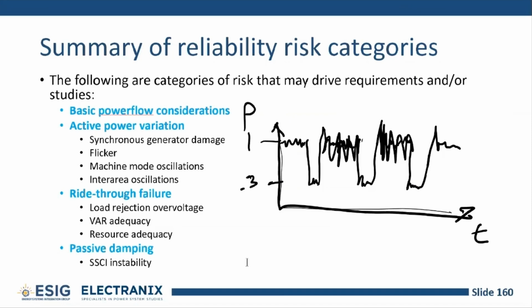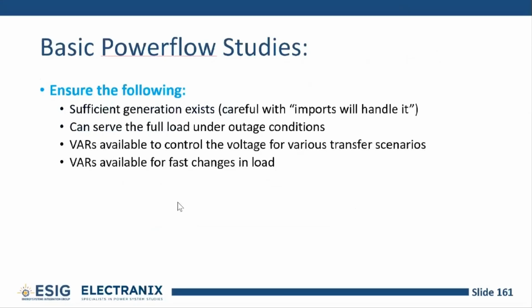But now these two completely electrically, geographically isolated plants are 100% coupled. So everything is working exactly in synchronism. So that's very worrying. When you're thinking about VARs and the whole plant ramping down, suddenly it might be a much wider area load rejection than you thought.